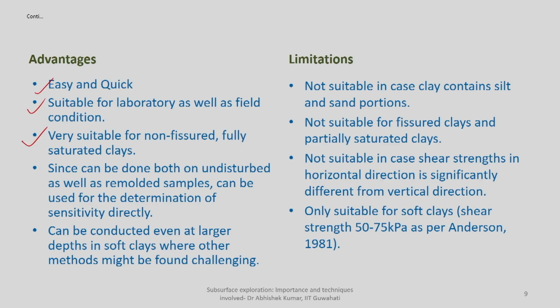Since the test can be done both in natural condition, or on a remolded soil sample created in the laboratory, it can determine the shear strength of both remolded as well as undisturbed soil samples. So, you will be able to determine the sensitivity of the clays directly. You need not go for any other testing. With the undisturbed soil sample from the field, you are able to determine the shear strength.